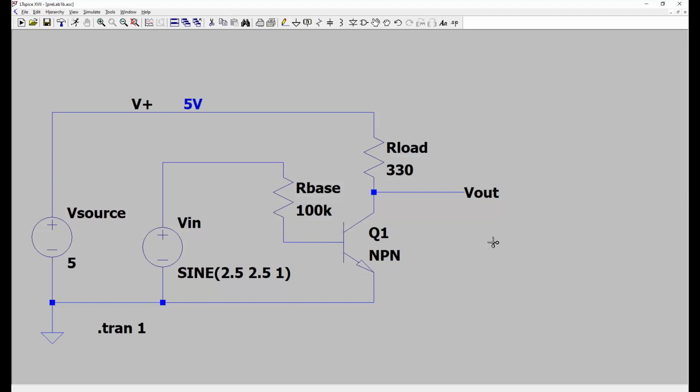When LTSpice does the transient analysis, what it is doing is it starts off at time 0, calculates all the values, increments a small fraction of the time that you've set for the simulation time to end, recalculates, moves forward in time, recalculates, moves forward in time, until it has calculated everything that happens in our case, 1 second, but the time is entirely up to you. After those have been calculated and stored, you can review it, similar to reviewing a data log.